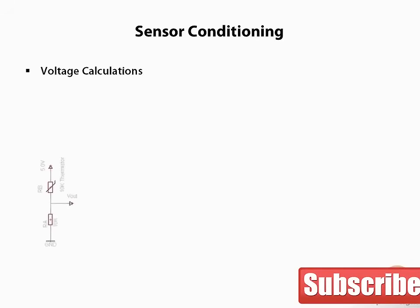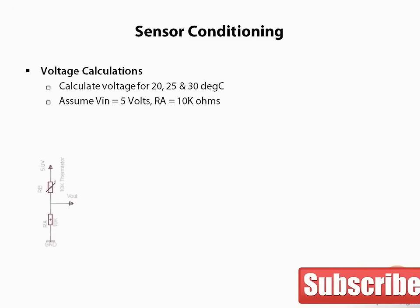Let's calculate the output voltage of our temperature sensing circuit for temperatures of 20 degrees C, 25 degrees C, and 30 degrees C. We'll assume that our process can accept a 0 to 5 volt signal, and we'll select RA equal to 10 k ohms. Using our equation, Vout equals Vin times RA over RA plus RB.